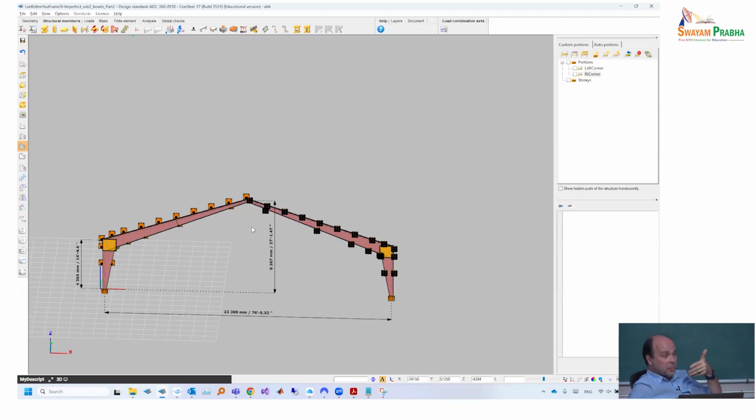And from the buckling shape point of view, this is a 3D problem, and this is full of torsion. The buckling mode is always the weakest part of the sections. That's what very many engineers say: oh, I don't need this complicated software, I'm always designing in 2D. Yes, but do they need to perform an LTB check? Probably, yes. Resistance is controlled by the out-of-plane.